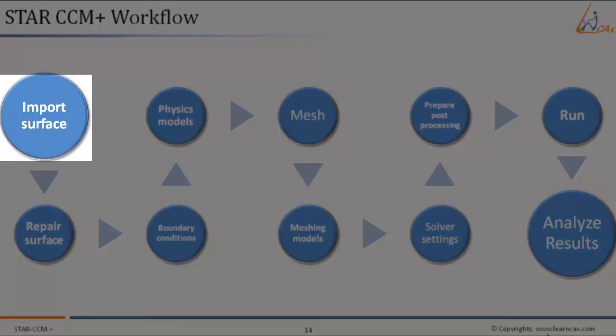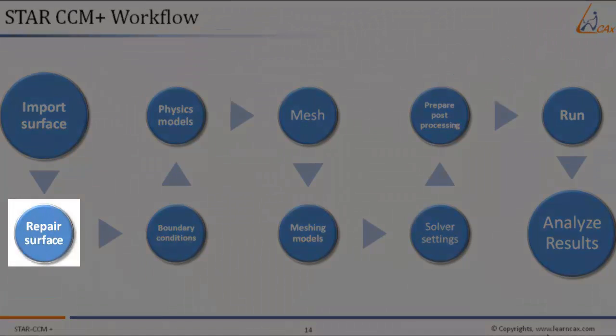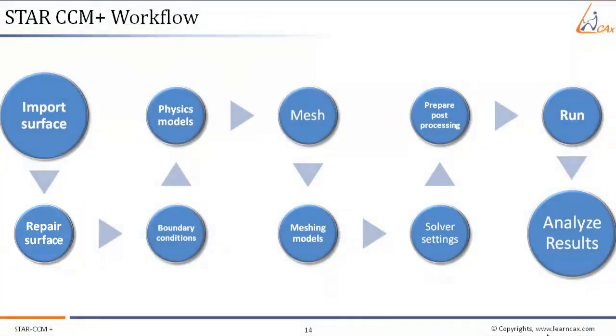The first step in the CFD workflow is to import a surface. This is the CAD file or model which is used to construct the CFD model. This CAD surface is not perfect and contains many errors most of times. For this, the next step is to repair the imported surface. In this, we close unwanted holes, patch surface error, and do many more things.